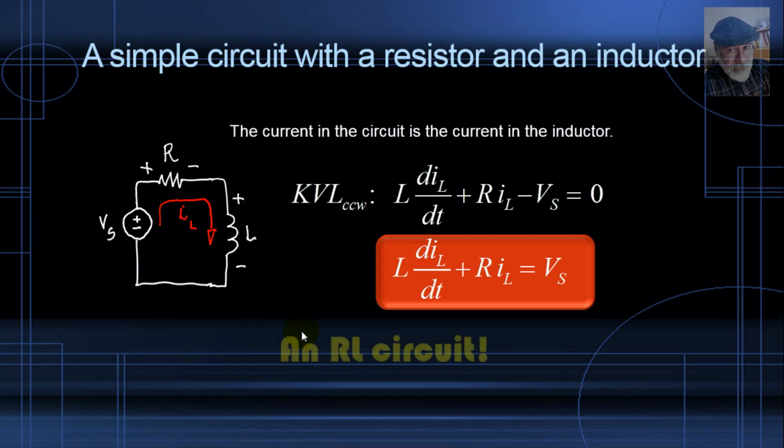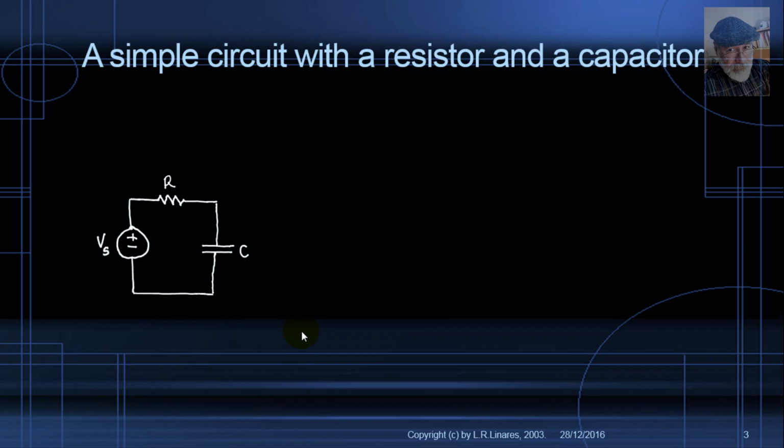Another example, a simple circuit that has one resistor and one capacitor, an RC circuit. Allow me to use MNA this time. I'm choosing this reference node and this node on the top, node 1. I'm promoting a binary node to the status of true node, node 1. The branch currents I choose arbitrarily, one entering node 1, one leaving node 1.